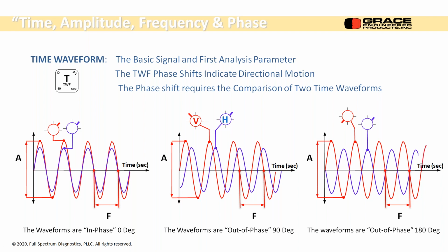Okay, that 90-degree phase shift is because the heavy spot has to go 90 degrees further from horizontal to vertical to be crossing the transducer. So now we see this out of phase time shift. Those are the 3 important phase definitions that we're looking at. Either it's in phase, it's a 90-degree shift, or it's out of phase. That's going to allow us to distinguish about 8 different faults.